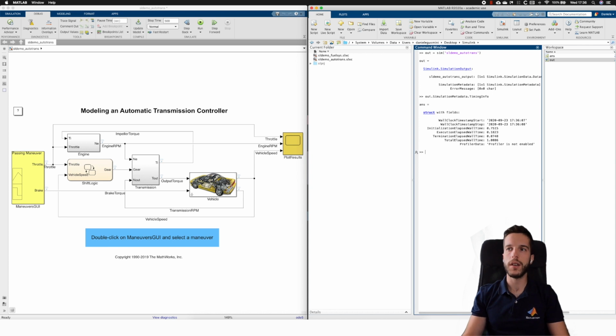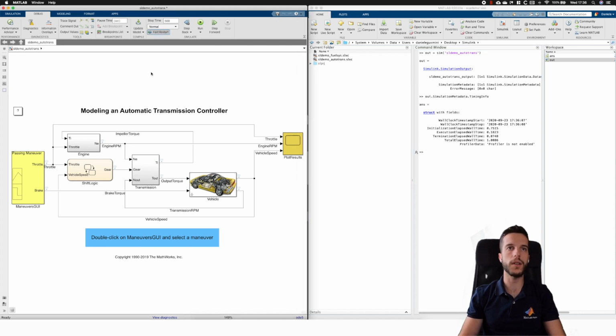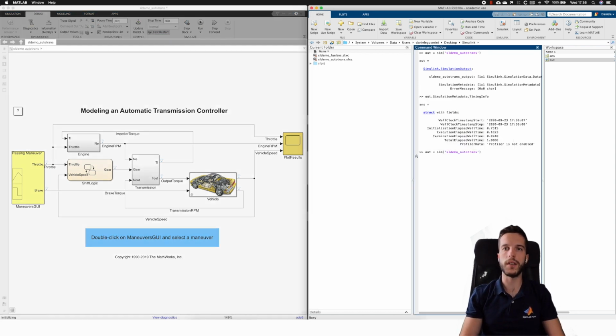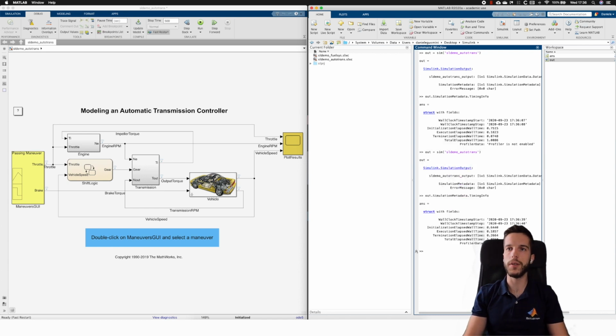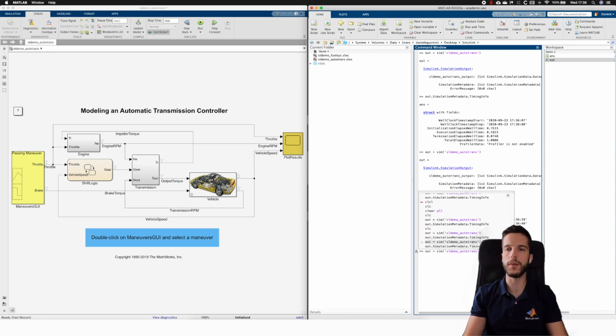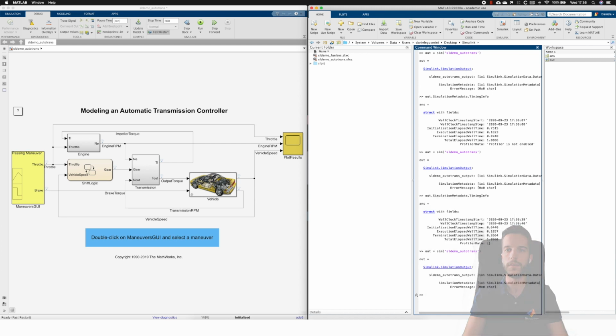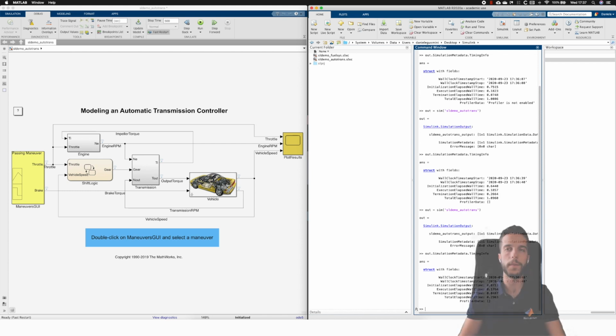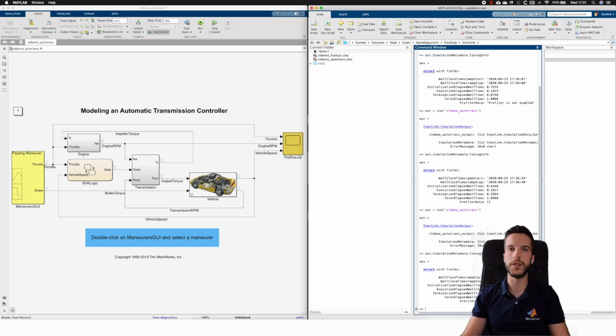that if we activate the fast restart and do the same thing, so we simulate and we check the timing info, of course the second time, the whole initialization elapsed time is only 0.07 seconds. In this case the model was very fast, but let's suppose that you have a model that takes many minutes to recompile. Of course, in this case you can save a lot of time. So let's return to the presentation.